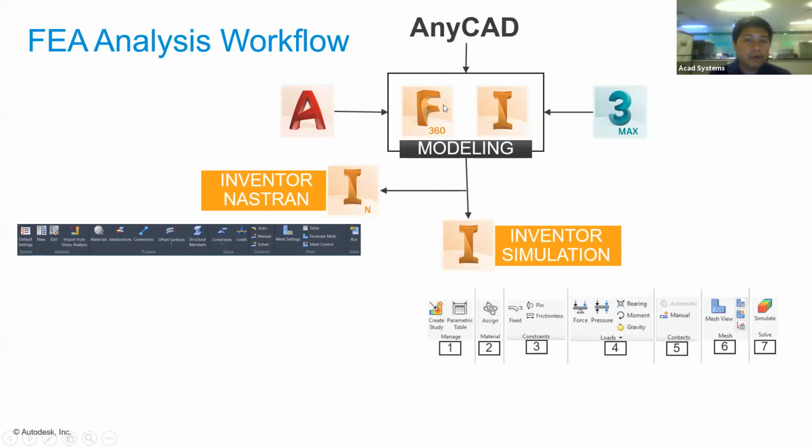It also has the simulation there. You just simply click Fusion 360 simulation. So there will be 2 methods. You can use either stress analysis or Nastran. Both can. Later, if you want to know the details of the difference between these 2, you may ask.